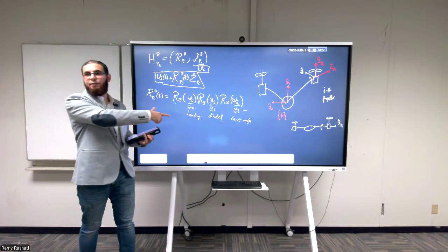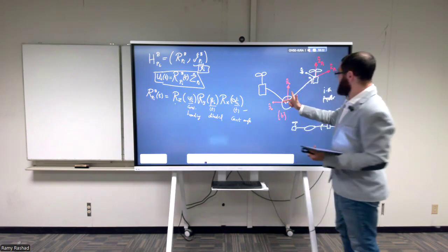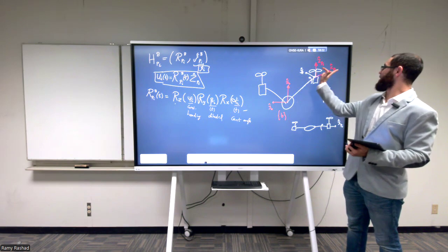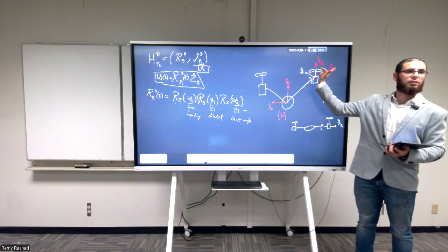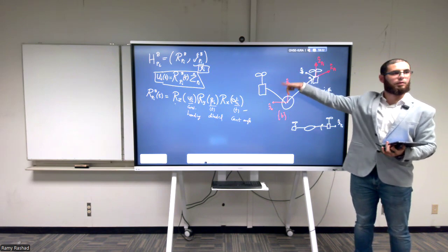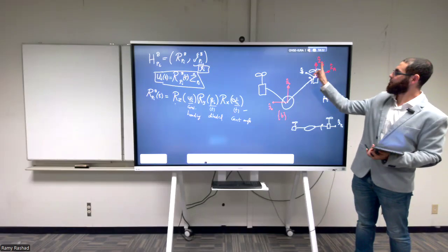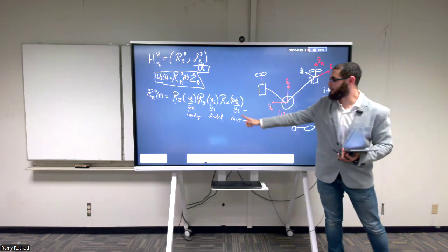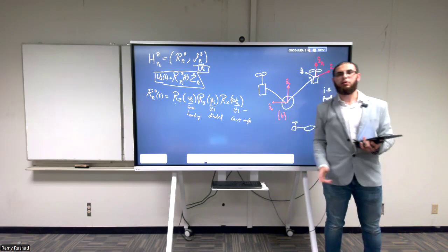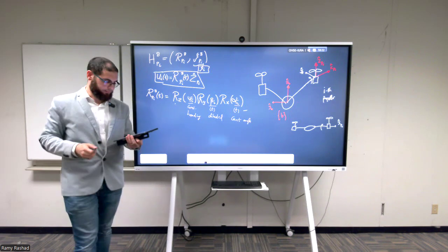These have physical meaning. The heading is simply the following. If I have the B frame, that looks like this, and then I take this frame and place the propeller like that, you see, I changed the heading, right? So this rotation means the heading. Then if I go here and start rotating the propeller like this, which is around the X, we call this the cant angle. If I rotate around the Y, we call this the dihedral angle. Okay, so these are actually physical angles to describe the orientation we're interested in.